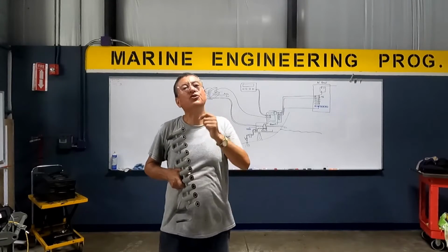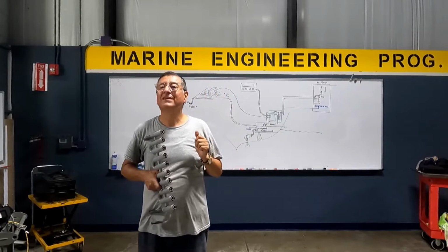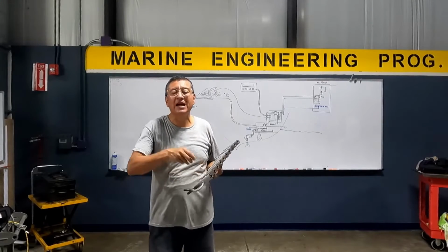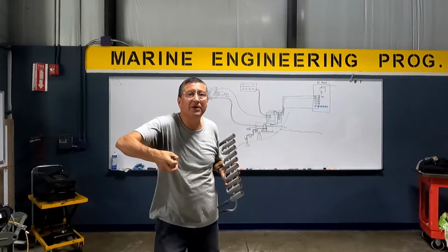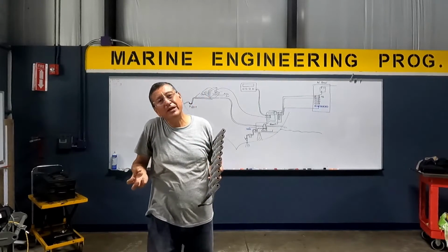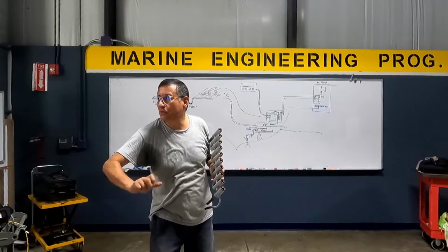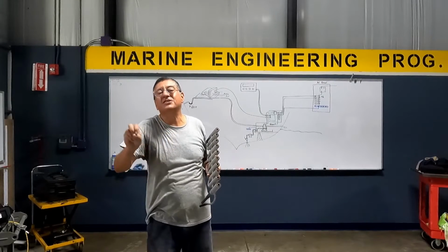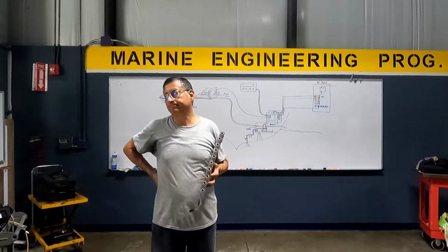If I have moisture in the refrigerant, it's because what? Leak. It's because I have leaks, and normally those leaks are on the fittings. On the fittings where you connect, you remember yesterday the high pressure and the low pressure. In the moment that you insert the fitting, you hear a hiss until you tighten the fitting. In that moment some refrigerant is going out, some humidity is going in.